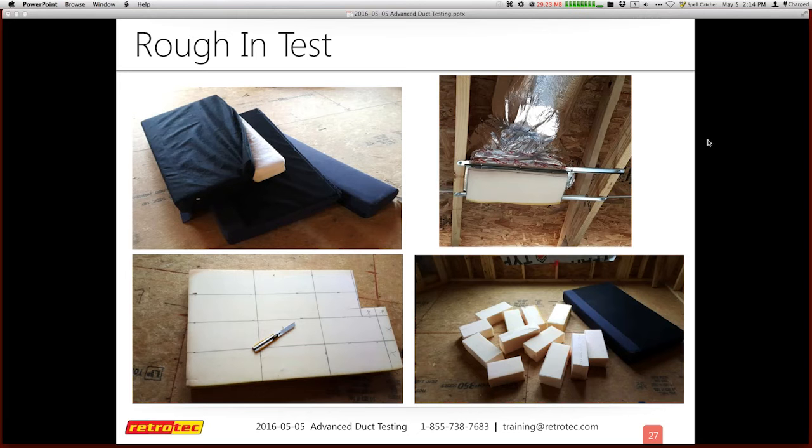Hey, Joe. Yes. On the foam front, I'm assuming they have to use unicellular foam, which means air doesn't flow through it. But there's a real easy test for that. You just suck on it. If you can suck air through it, it means it'll leak. So I would think that the accumulated leaks of all, if it was open cell foam, would be so much that the ducts would show up too leaky, unless you do the trick that I think you might have shown here. No, actually, you're not showing that. You just take the foam and you cover it with a thin piece of saran wrap or plastic and then stuff it in there.